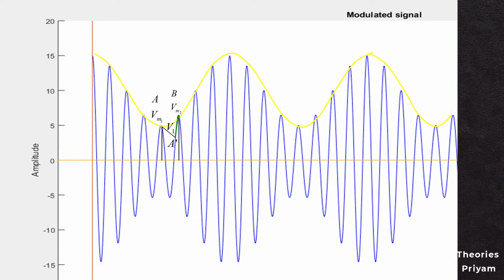After that, again the capacitor will discharge across the resistor R up to the voltage V2 at the point B prime when the diode is in the reverse bias. This process will continue as the capacitor charges to the point C and discharges to the point C prime until the capacitor charges to the point E and discharges.